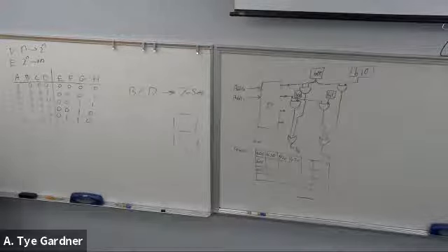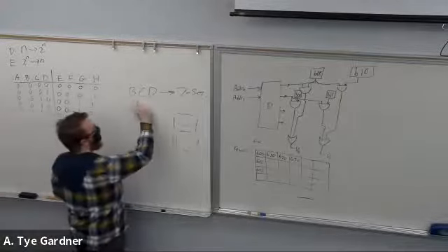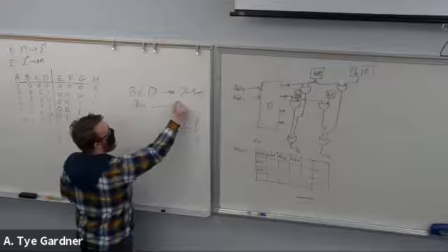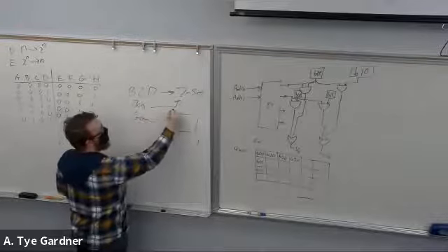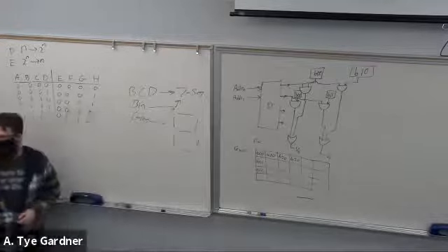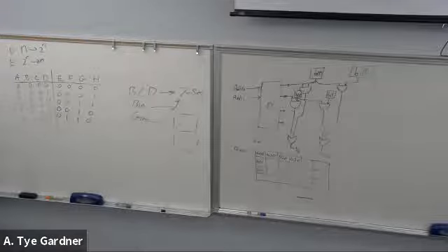We could also do just straight binary to 7-segment. We could also do gray to 7-segment, right? We could convert codes all sorts of ways. We do it the same. Write out the truth table, fill in the K-map, do the simplification, build the circuit.